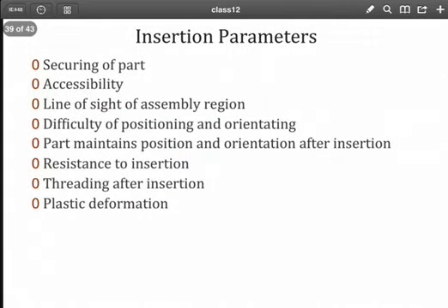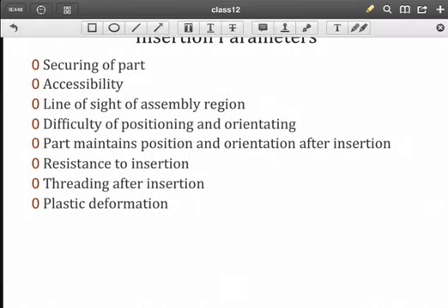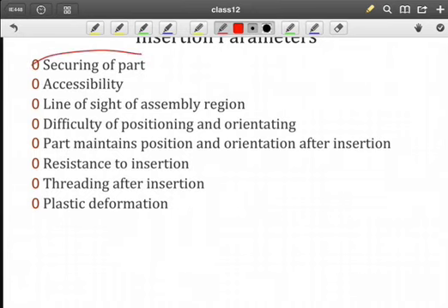For the insertion parameters, once we have our handling parameters, we can look up the time for handling. We're looking at some other considerations. First of all, the securing of the part. Now, when you think of securing the part, what happens when you release the part after you've assembled it into its location? Does it tip over? Is it going to be secure? If the assembly is bumped, will there be a problem?